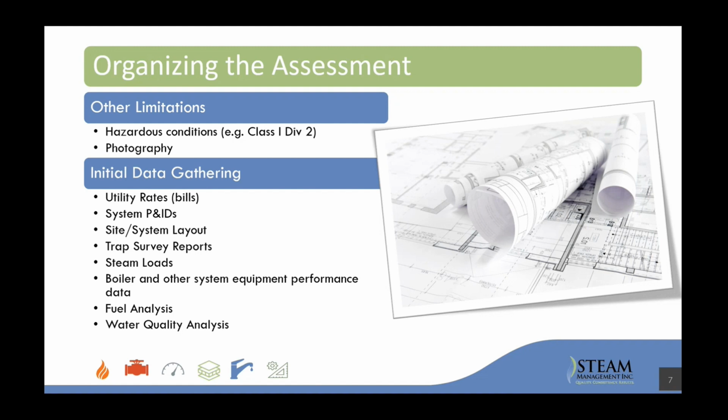Steam loads, how are they operating the system? Any boiler and other equipment performance data, or just model numbers, and we can look that type of stuff up. So it's great to know as much as you can about all the equipment involved. If they have a fuel analysis or higher heating value of the fuel, and water quality analysis.